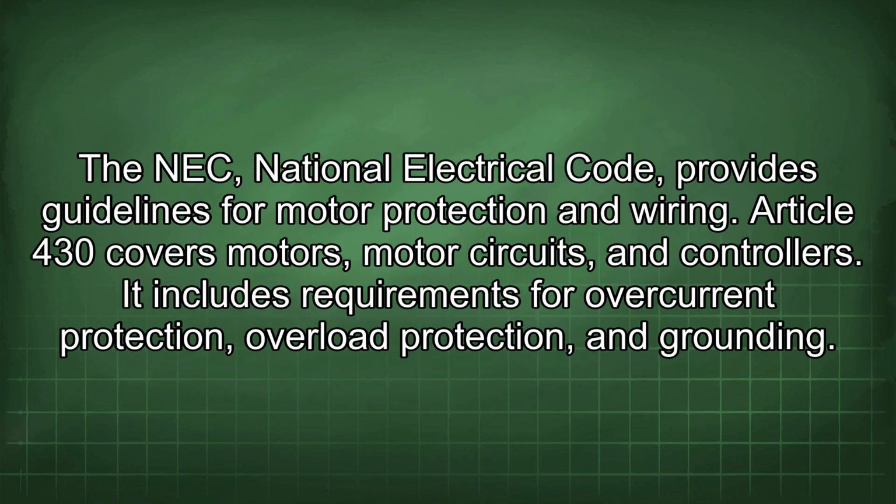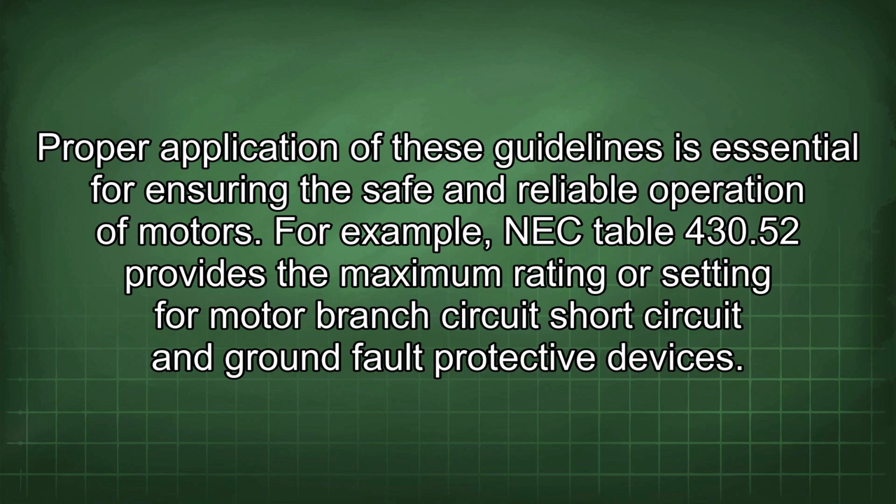The NEC, National Electrical Code, provides guidelines for motor protection and wiring. Article 430 covers motors, motor circuits, and controllers. It includes requirements for overcurrent protection, overload protection, and grounding. Proper application of these guidelines is essential for ensuring the safe and reliable operation of motors.